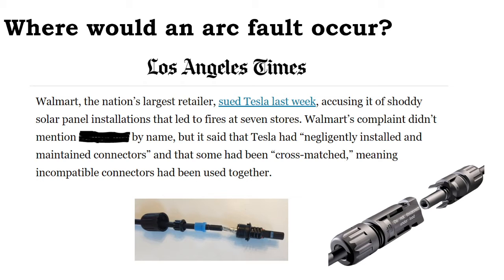And that's, I guess what I would say in the context of workmanship. You need to make sure your connectors are compatible. They're usually compatible, but not always. There's a 600 volt connector and a 1000 volt connector. And if you're using the 600 volt one instead of the 1000 volt one, even if the connectors are compatible, that could create a safety problem down the road.